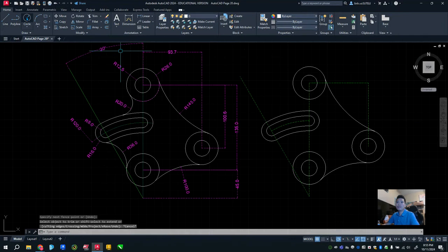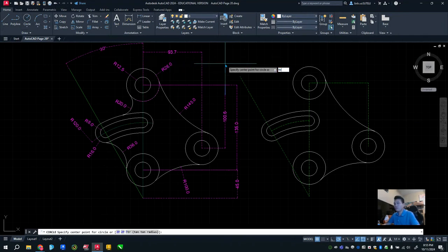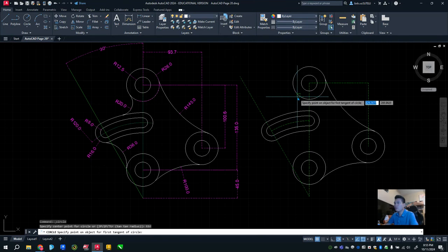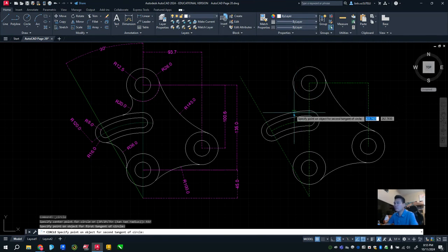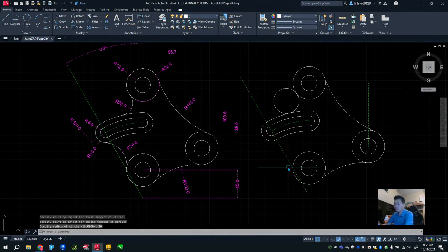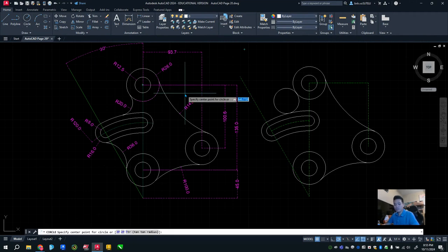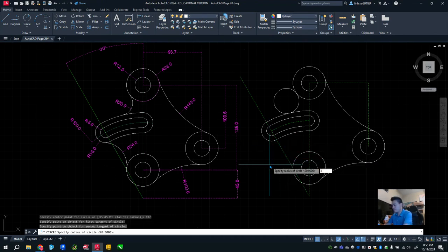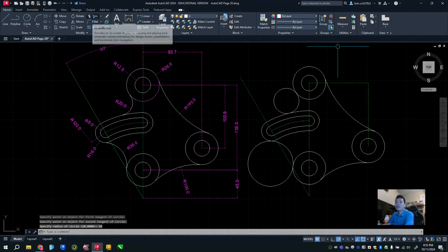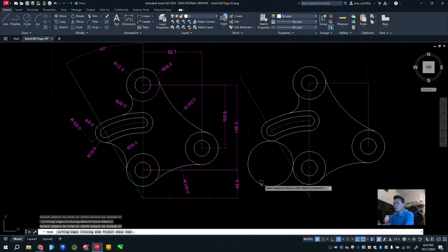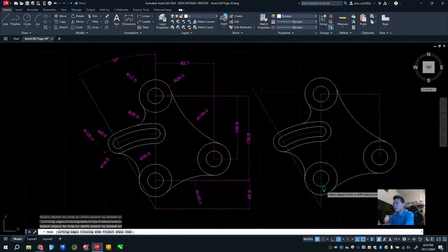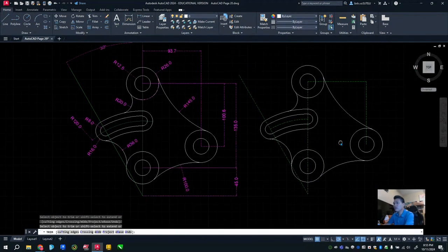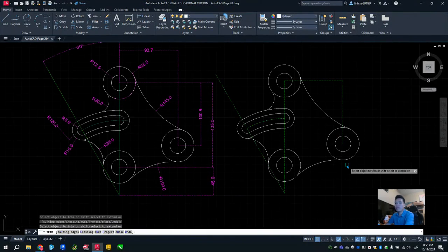Once you have that, all you have to do is go in and do tangent radius. We're going to do the top there, bottom here, and the radius will be 20. Then we're going to do tangent radius one more time, and it would be 36. So here we are, there we are, and 36. Then we can trim out the section we don't want, and double check everything here. The shape is identical, everything is complete.